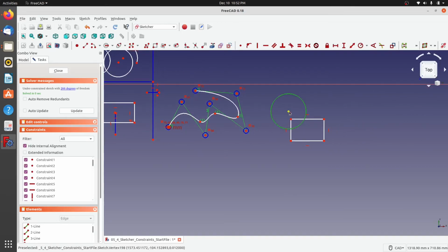Again, we can freeze this shape too. If you want to freeze this shape like this, we can click on it and then this shape is frozen, so you cannot change it anyhow. Now, if I go in here and delete those frozen constraints, we will be able to edit that rectangle again.